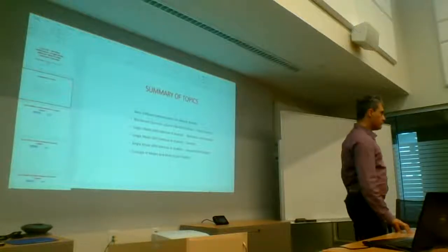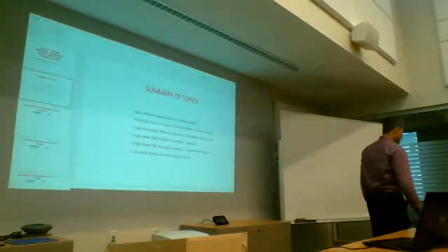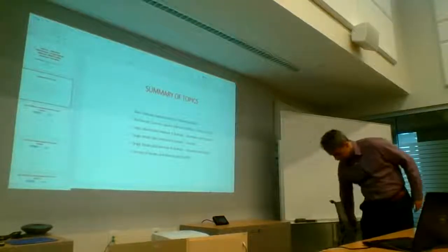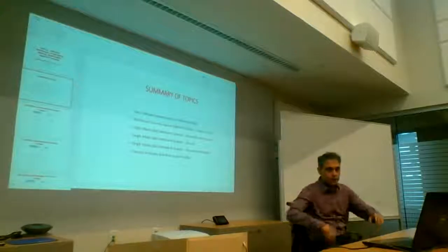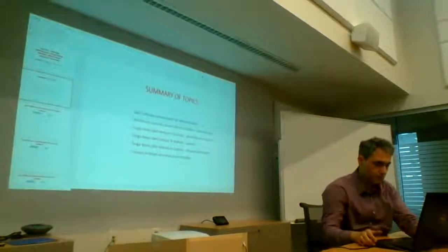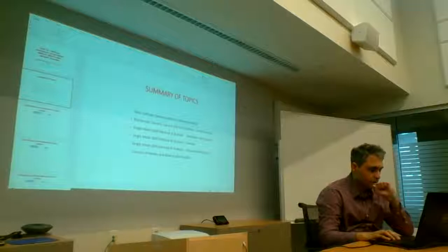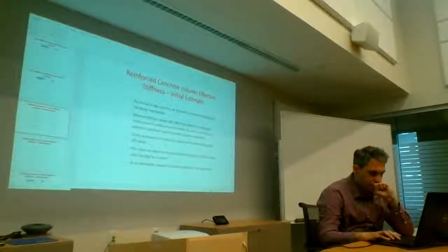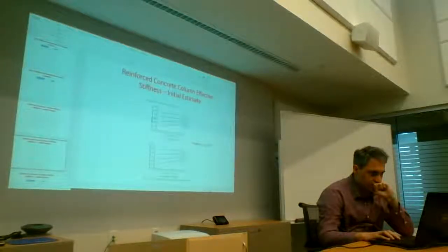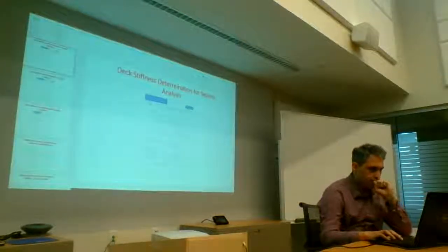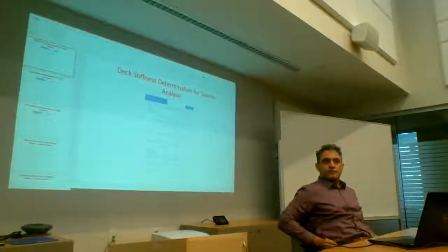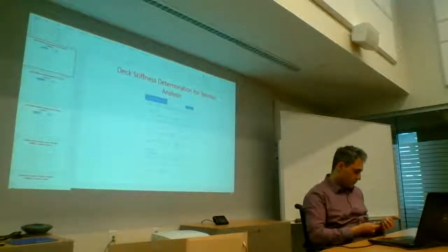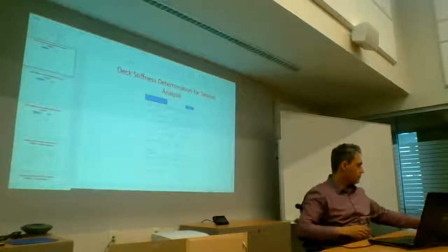Through IFC, it is 100%? 100% or it is 80%? Because from my experience, it shouldn't be. Transfer is there, but it's not 100%. What is missing? For example, whatever model you are getting from Revit to SAP, you cannot 100% utilize that one. You have to do 20 or 30% manual work to make it suitable to run as a structural model.